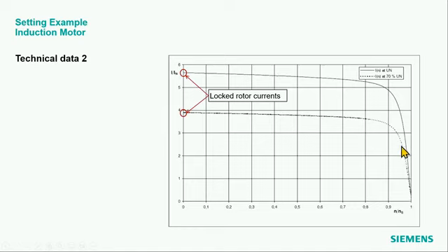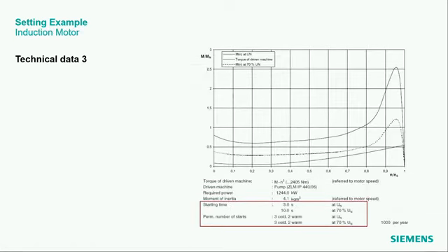And somewhere here I will have the nominal slip and the nominal conditions. Here I have the current over the slip. This does not give me an indication for the time, but from here I could also get the startup currents. It's always the current at the beginning of the startup. This is the current which we call the starting current, on which we base everything.